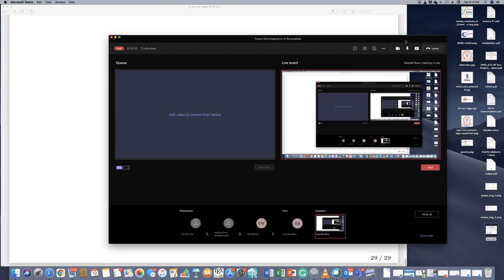That may not be seen here. And the good thing is the turn off of the diodes, right? The turn off, or the reverse recovery of the diode, is a function of how fast the current in the diode is dying. Because of this inductor, the speed at which current will be coming down across those diodes is a function of those inductors, so they will actually slow it down. So the reverse recovery effect will be lower in this kind of topologies.